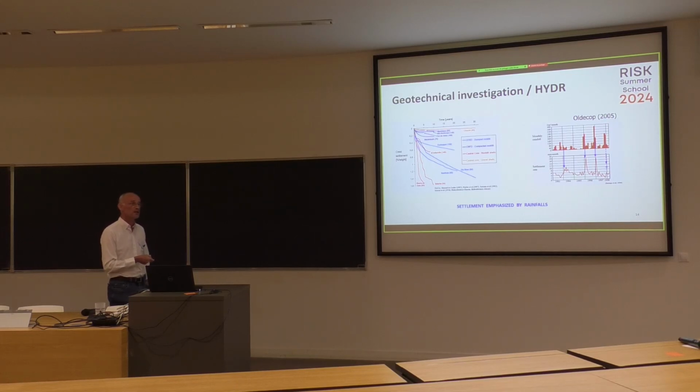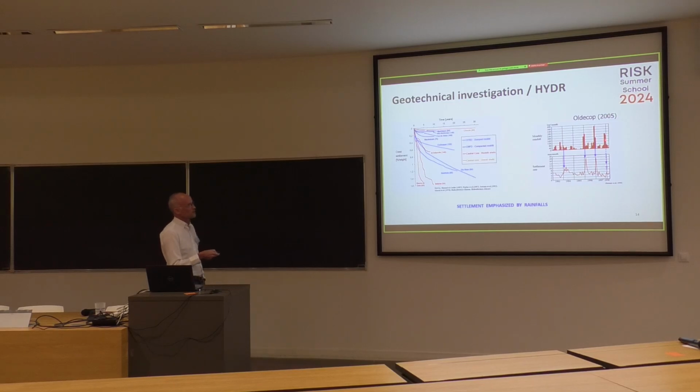So it's not negligible at all. And when we correlate the rainfall with the settlement, you see that there is a strong correlation between both. So yes, there is an interaction between water from the rainfall or from the reservoir and the behavior of the rockfill.